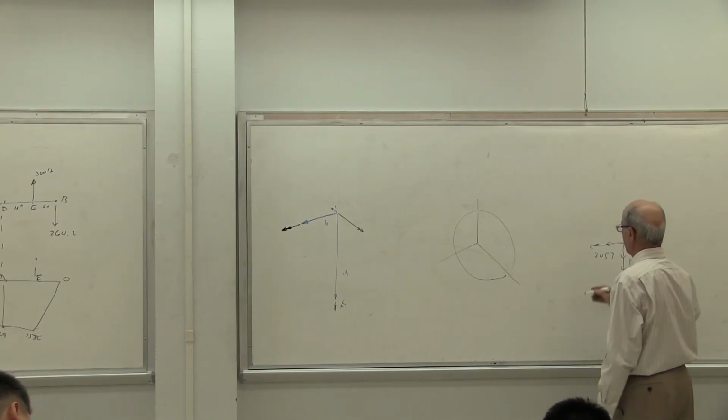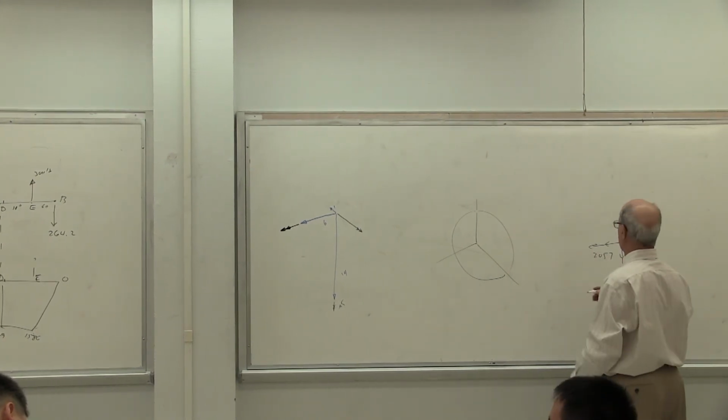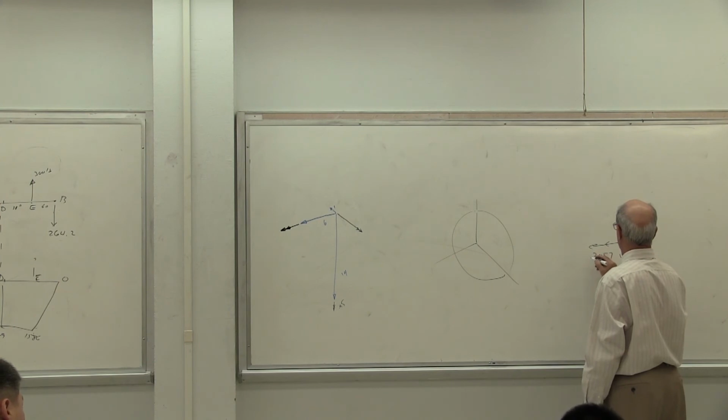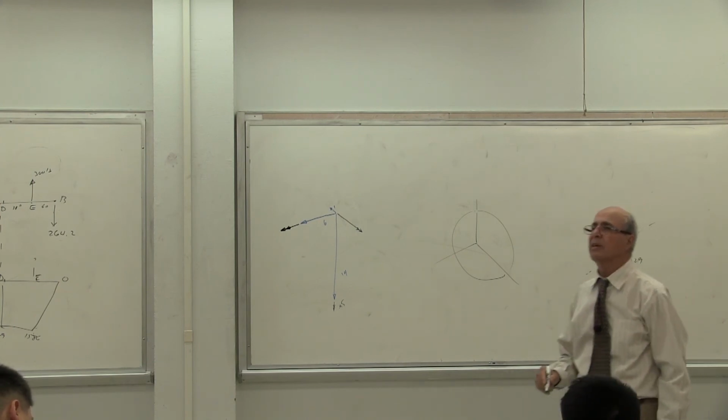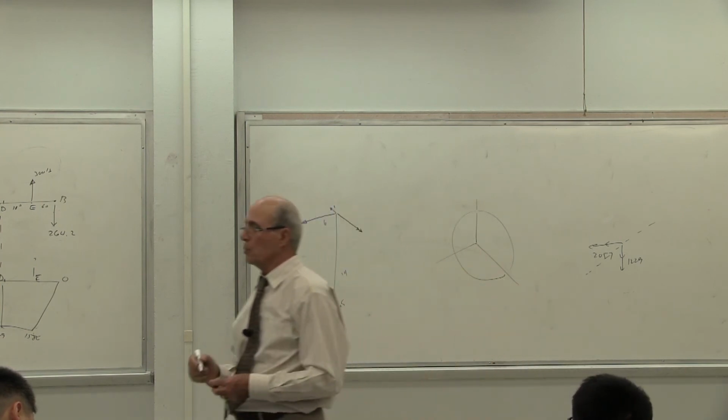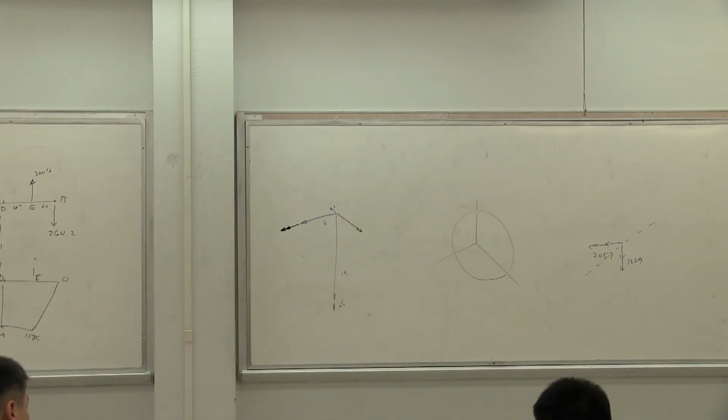If those are all correct, of course, this depends whether you draw it in the right direction or not. And this will be the resultant. Is that correct or not? Yes? Based on those numbers, and you can calculate where that falls if you want to. Is that correct or not? Yes? So you know the exact point, actually. If you want to put a strain gauge there to measure strain, you may want to put it there, because that's the highest point with the highest stress.